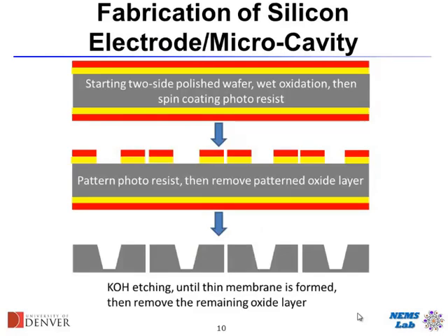Now the fabrication process, extremely simple, just one lithography step. Open up some open areas on a silicon wafer. We use the double polished silicon wafer. The reason we use double polish was we want to have a smooth surface so that when we thin it down, we don't end up having holes in it before we can get to a thin enough thickness. At the same time, the etching can be used to thin down the boundaries between different chips, and so it will be easy in the end to break them off.